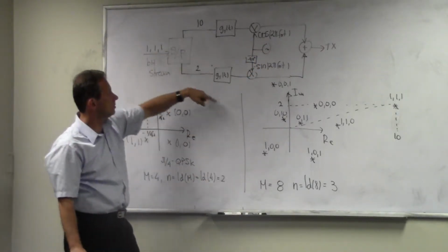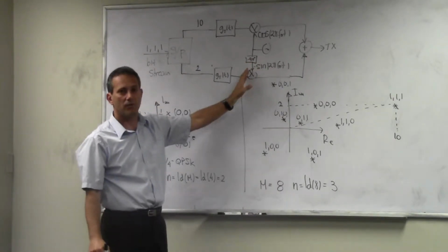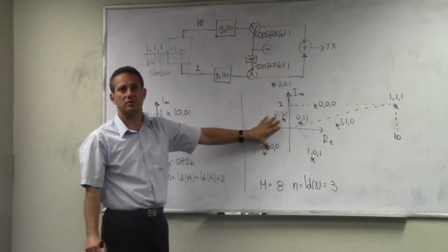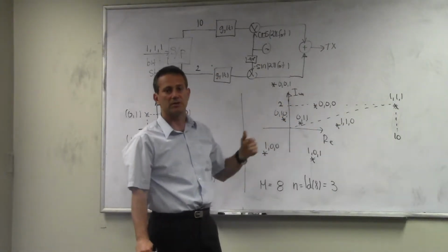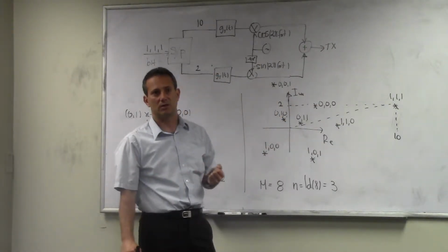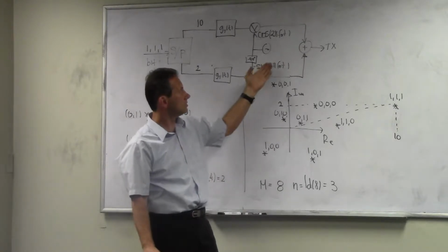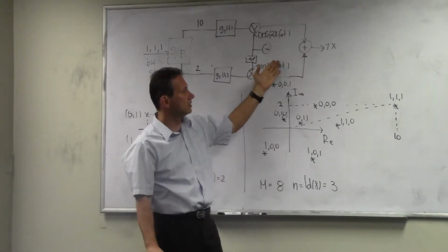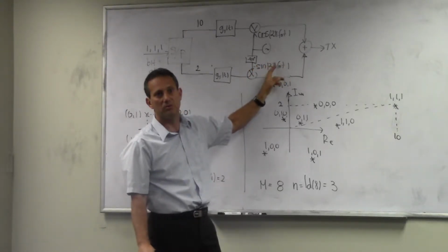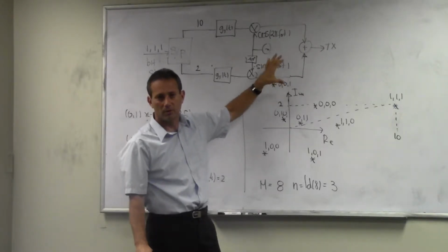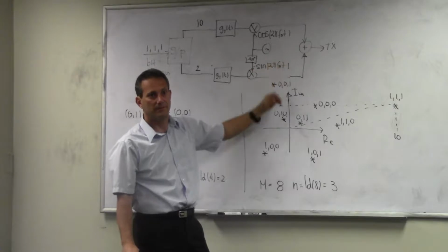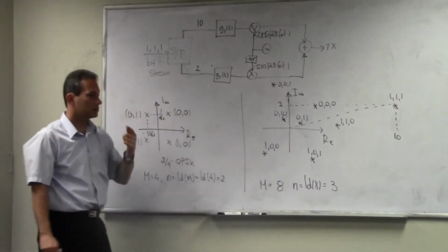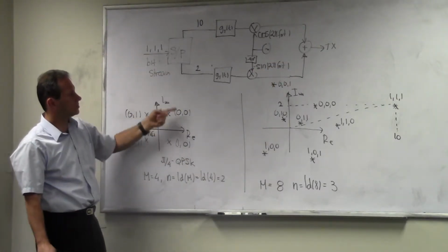Because sine and cosine form the basis of the two-dimensional signal space, you can pick any point on this board and express it in terms of sine and cosine. So that's why this is a general case of the modulator that can be used for QAM and PSK signals alike, right? Does that answer? So you don't change, because it's two-dimensional.